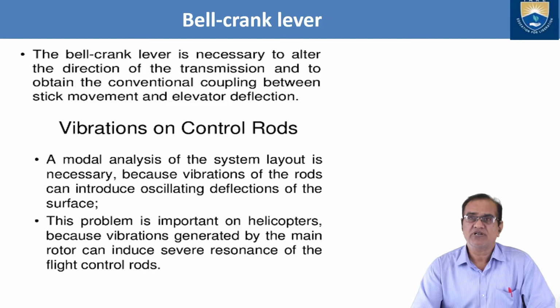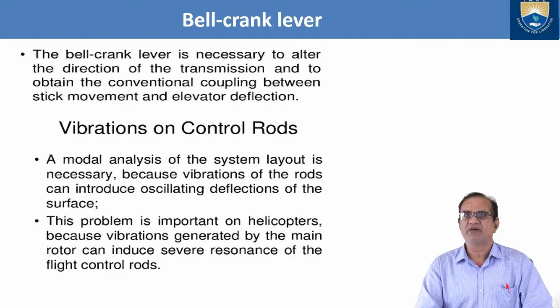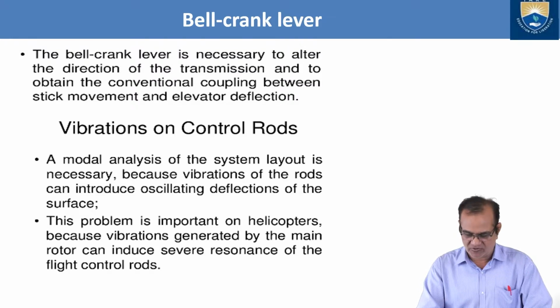Vibration on the control rod. A modal analysis of the system layout is necessary because vibration of the rods can introduce oscillating deflection of the surface. This problem is important on helicopters because vibration generated by the main rotor can induce several resonances of the flight control rods.